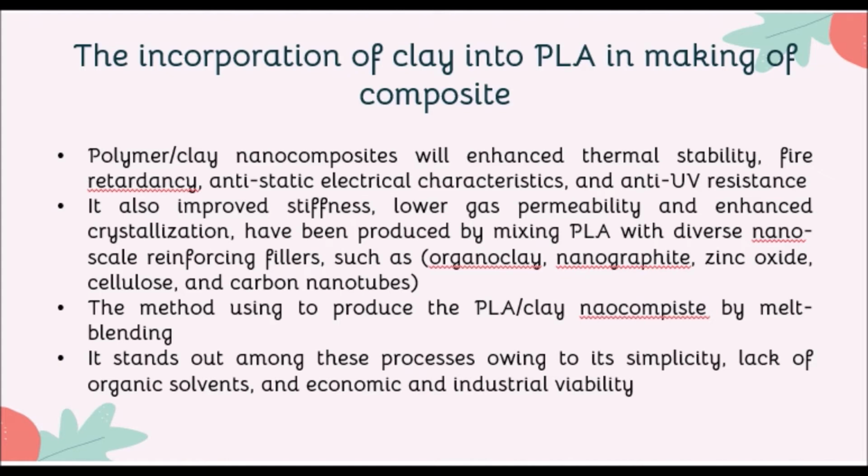So the next is the incorporation of clay into PLA in making of the composite. The polymer clay nanocomposite will enhance the thermal stability, fire retardancy, anti-static electrical characteristics, and also anti-UV resistance. It also improves the stiffness, lowers gas permeability, and also enhances the crystallization. It has been produced by mixing the PLA with diverse nanoscale reinforcing fillers such as organoclay, nanographite, zinc oxide, cellulose, and carbon nanotube.